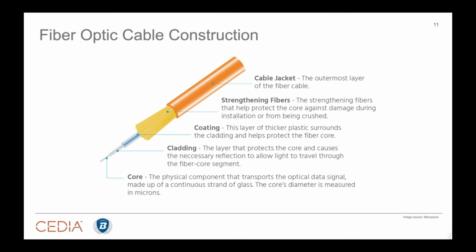This is why you have a pull rating over 100 pounds. And in fact, in some of these cables, pull rating up to 220 pounds. They are strong. That strengthening fiber that, trust me, you can't cut with the scissors. You can't cut with a knife. You got to use Kevlar shears. It really makes the cable strong.